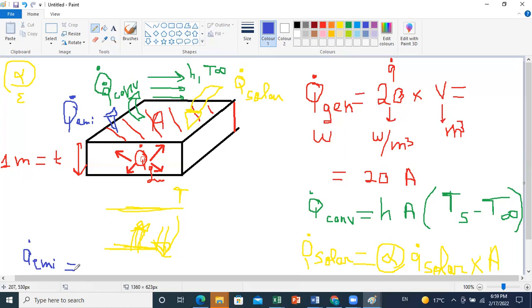What is challenging a little bit is that we changed the form of radiation you are familiar with. In general, you have two surfaces, one at temperature T1, the other at temperature T2. Because of this difference in temperature, this surface will emit a radiative flux equal to epsilon of the surface times the Boltzmann constant times the area of surface 1, times the temperature T1 to the power 4. So this is in general how you express your flux emitted from this surface.